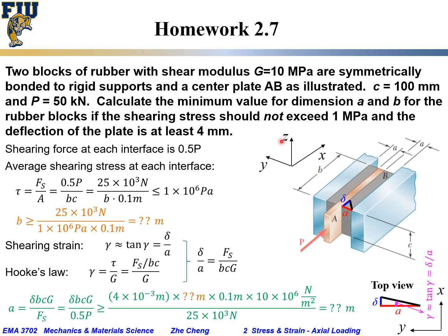So that is the situation. We want to calculate the minimum dimension for A, thickness of the rubber blocks, and B, length of the rubber blocks, if the shearing stress within the rubber block should not exceed 1 megapascal, and the deflection of the plate.